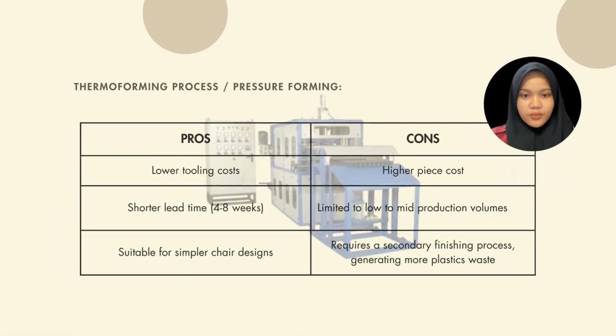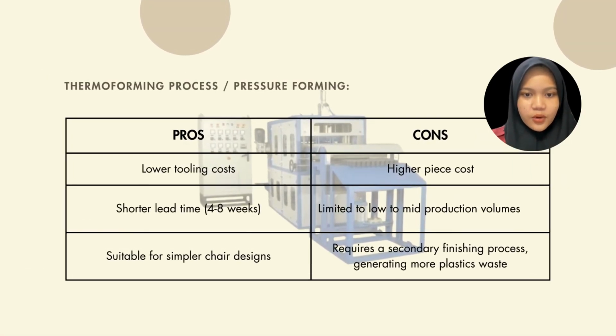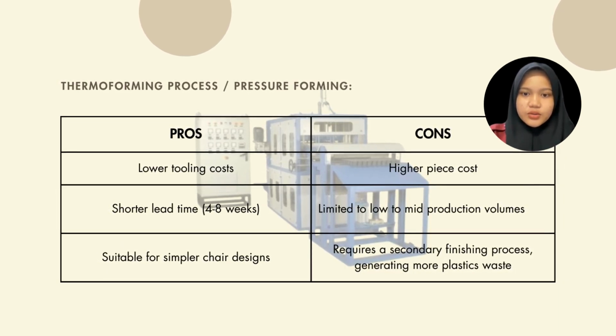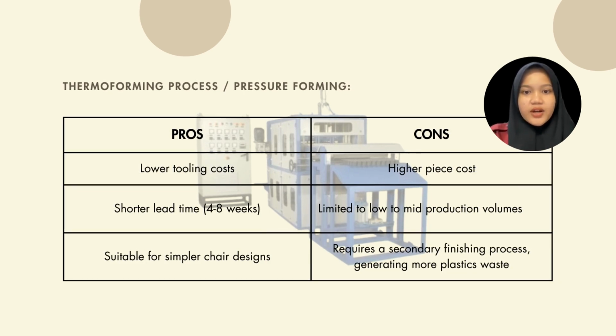For thermoforming, the pros are a lower tooling cost compared to injection molding. Thermoforming requires simpler and cheaper molds, making it a viable option for low to mid production volumes. It also has a shorter lead time, within 4 to 8 weeks. It is also ideal for simpler designs.